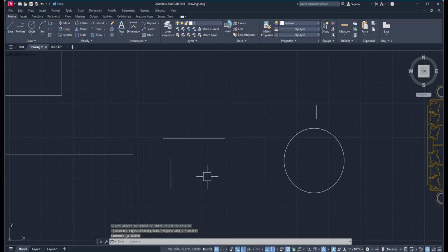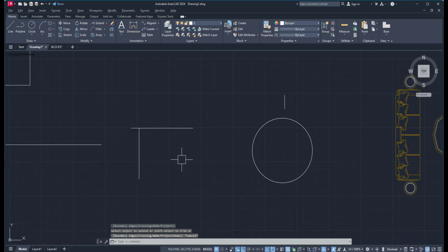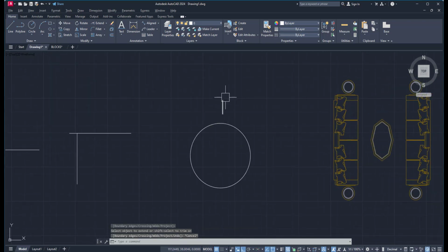This is how we operate with the shortcut. I just do Ctrl Z. But if you follow the method which is there in the modify option, take the extend command. Now it is asking me to select the object, extend it and hit enter. Also I just want to copy this single line in a polar way, as I already learned the polar array.